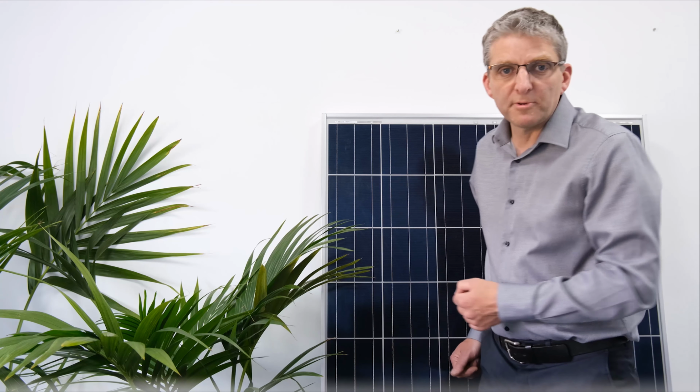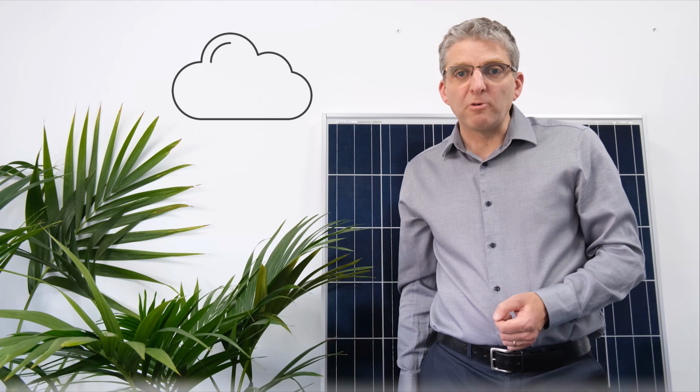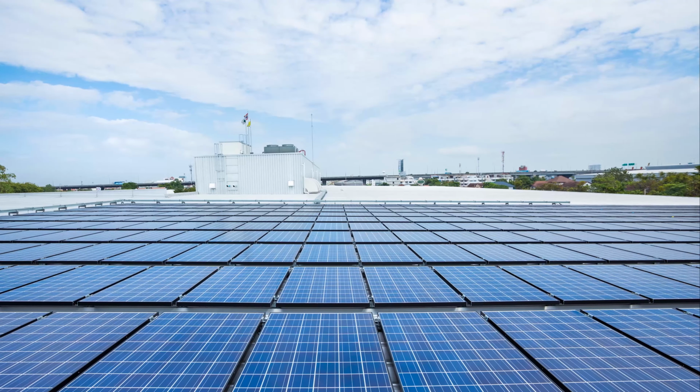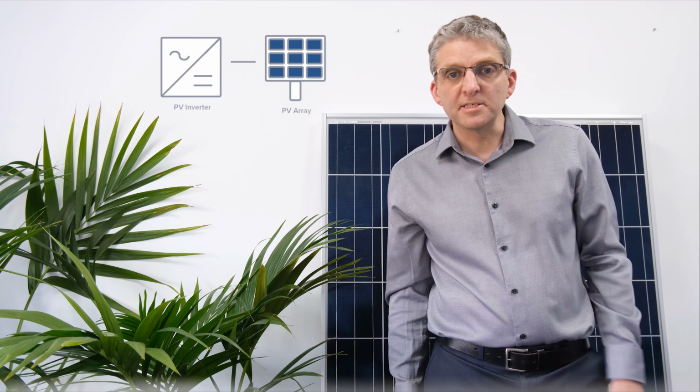Now this solar module can produce a couple of hundred watts when it's sunny, and quite a lot less when it's cloudy. To get more power from the system, you just add more solar modules, and this makes what we call a solar array. The electrical output from a solar module is DC, direct current. And before we can use this in our buildings, we have to convert it to AC, and that's done using an inverter.